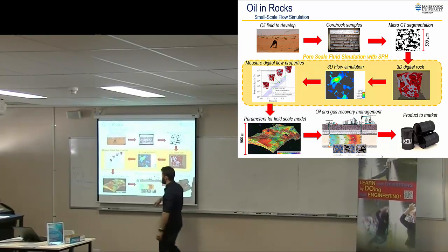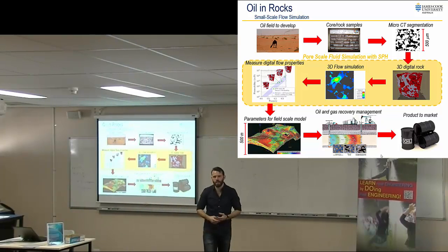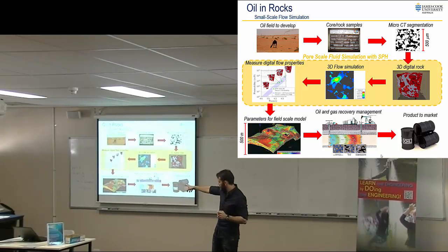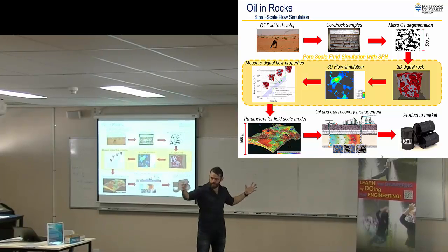Because when you've got many kilometres, so the biggest oil reservoir in the world is in Saudi Arabia, and it's tens of kilometres across. And when you've got a simulation of one of those field scale models, they run that with close to 1 billion degrees of freedom in the elements on the supercomputers that they have. Saudi Aramco is the company that manages that work. And one of those elements is the size of this whole building combined. So not this room, this whole building is one of those elements, and they've got 1 billion of those.